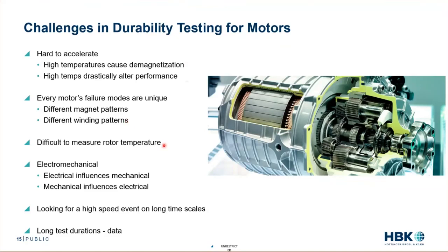It's really difficult to measure rotor temperature. And when we think that the magnet failures are largely driven by that Curie temperature, and that Curie temperature is local to the rotor, if we don't have a good way of measuring rotor temp, that becomes hard. We have to use mathematical estimations, and there's inherent error. HPK does have some cool methods for measuring rotor temperature. I'm not going to talk about them today, but if you're serious about it, I would love to have that discussion.